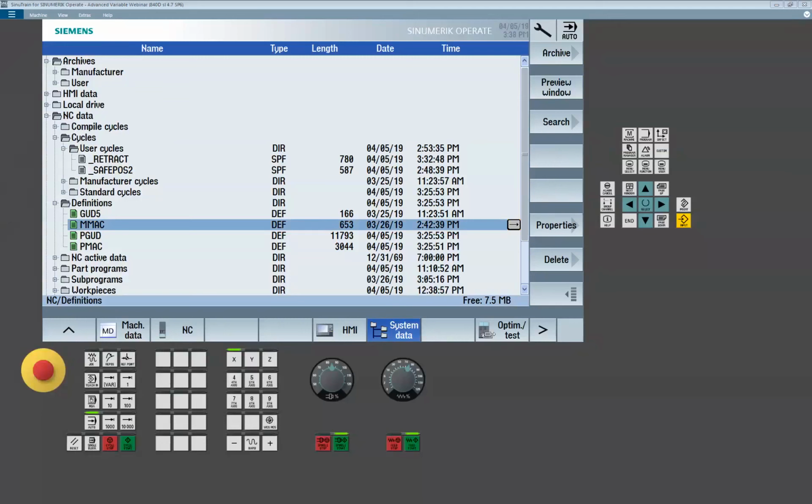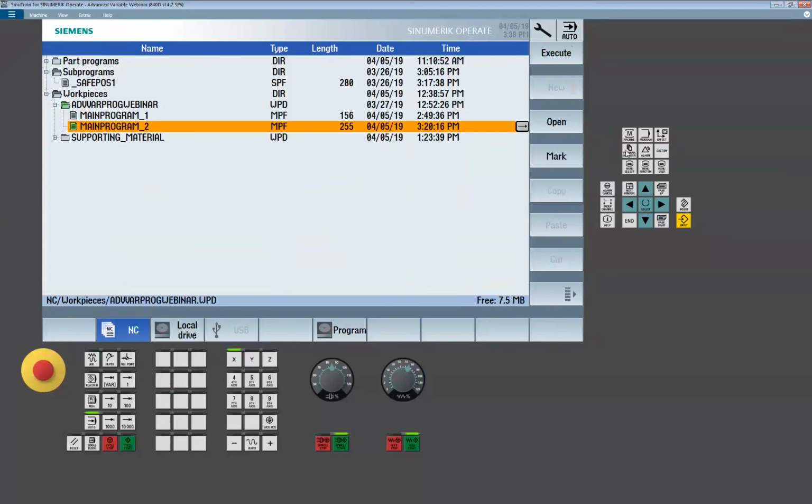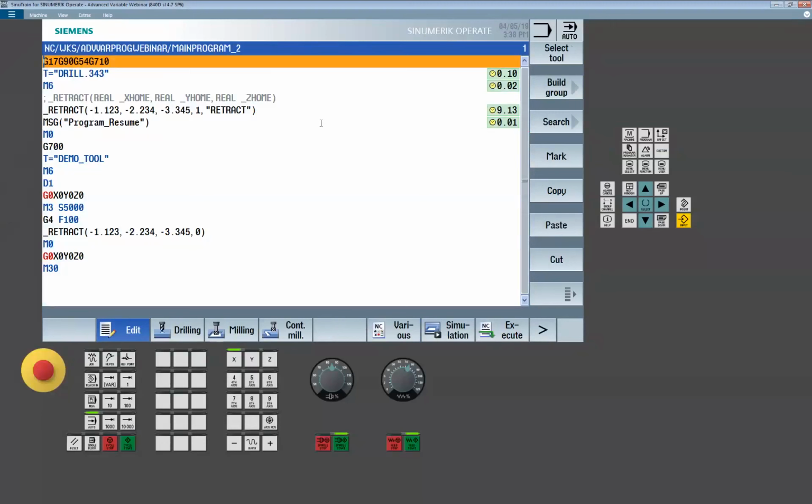I think it's 0, because if you remember before when I was playing around with this, I didn't have the tool value set to 0. I left it blank, and it treated it as if it was a 0. So what Alan's referring to here is, I'm in my main program and we built a cycle, but I neglected to put it in yet. I believe it gets treated as a 0. So you want to be careful with that.